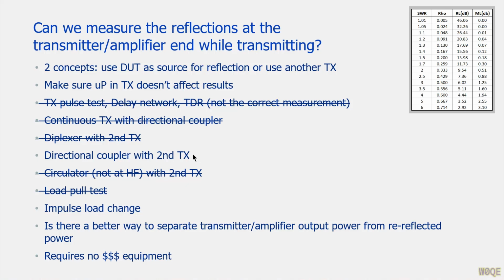That's half the difference in frequency. If the difference in frequency is 20 kilohertz, that's 50 microseconds, and in 25 microseconds, you run through all the phases. So I can look at this and see the results of all the different phases of a certain reflected power coming into the transmitter if I wanted to. This one, I can't do that. I have to do each load independently. But this one gives me the ability to guarantee that I'm measuring it at the right frequency.